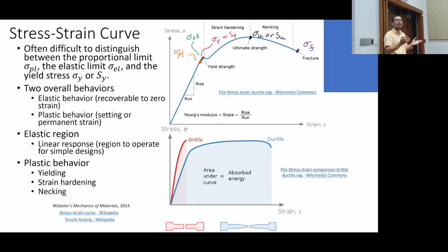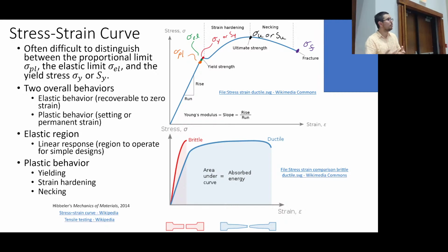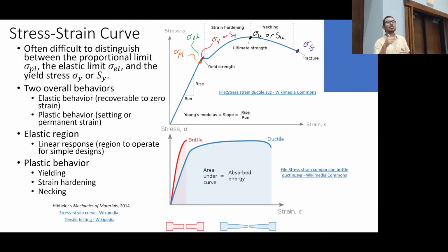So if the yield strength is 100 megapascals, and the yield strain, which is not a term you'll hear me use very often, is 0.1%, right? 0.1% is 1 over 1,000. So I had 100 megapascals over 1 over 1,000. That's 1,000 times 100 megapascals. Boom, megapascal, gigapascal, right? That's it. So now I have 100 gigapascals as my elastic modulus. That's all you've got to do. All right, and so you can do it.